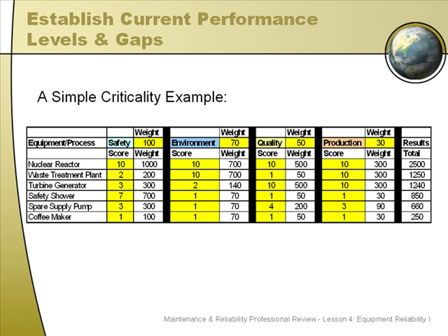Really what we're talking about there is if you have a piece of equipment that has a special reason to be considered high criticality, then you should give it some weight. For instance, I'll give you an example. Many facilities, because of their size, have electric golf cart type equipment for moving personnel around the facility, and generally those are considered a convenience item. But if you have a person on your staff who has a disability and isn't able to walk or move around in an efficient manner, then you need to give them access to a cart like that, and normally an electric golf cart would be a low criticality piece of equipment. In this situation, however, it's vital to that person's success, and it would be considered high criticality. I'm sure you can think of other examples similar to that.